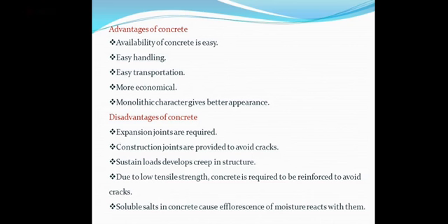Due to low tensile strength, concrete requires to be reinforced to avoid cracks. As I told you earlier, concrete is good in compression but weak in tension. To resist the tensile stress, we have to provide reinforcement so that the cracks will be reduced. Soluble salt in the concrete causes efflorescence when moisture reacts with them. Because of the salt particles in the water, the white type of efflorescence will come on the surface area. That is salt efflorescence.